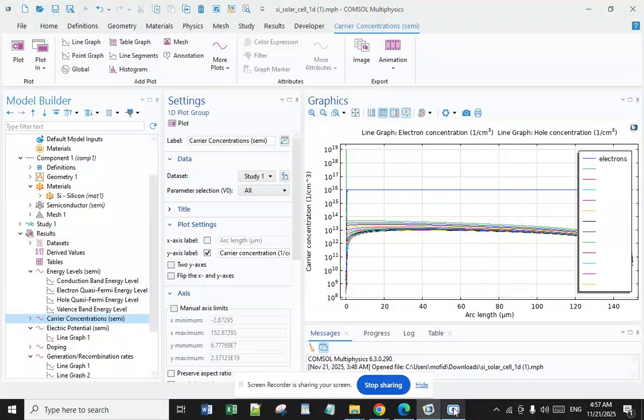We can then extract electrical power by applying a small forward bias to the solar cell. The power is given by the product of the applied voltage and photocurrent. The goal of the model is to predict a silicon solar cell's behavior under this forward bias, with an applied voltage between 0 and 0.6 volt.